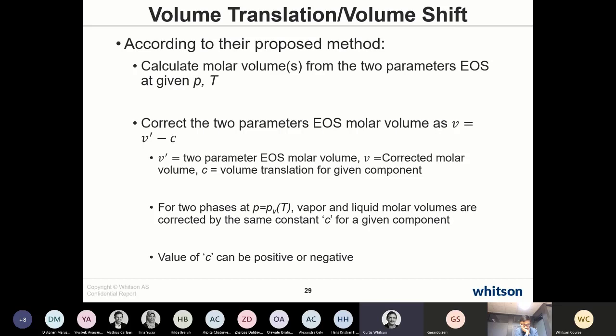So that was one approach, and then Keith Coats presented a paper in the early 1980s where he introduced the idea of correcting the A and B of all the C7 plus components as a single parameter, a single correction term. And another two correction terms, which was the A and B of methane. And then his fifth parameter was the binary interaction parameter between methane and C7 plus.